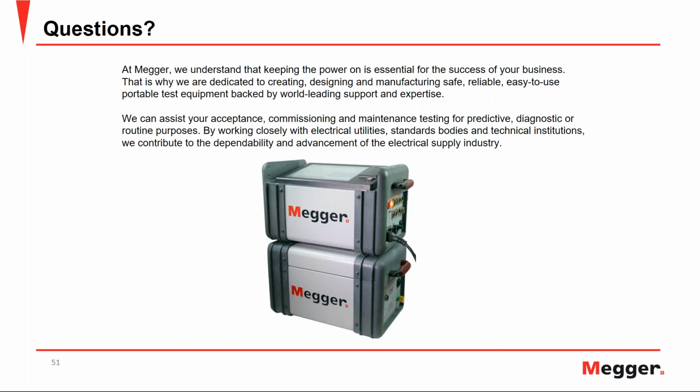Well, in general, if we look at IEEE documentation, the IEEE field guide for transformer testing, we'll see there are a couple factors to take into account to determine what is the limit for the power factor. If we are talking about new units, the general guideline is 0.5%. Although it also depends on both the voltage rating of the unit and the type of insulating liquid of the transformer in question.